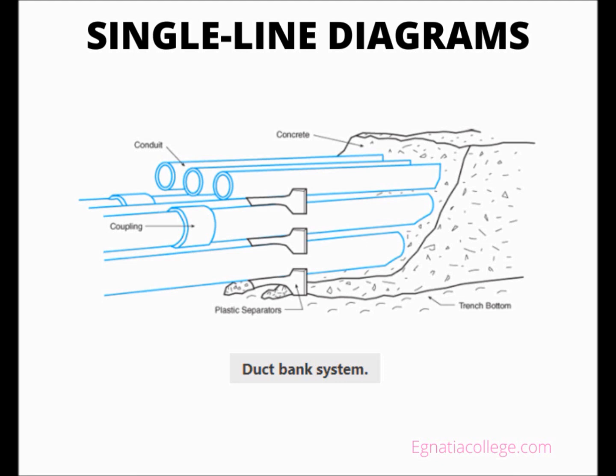And the existing electrical distribution plan on drawing E2 shows only a portion of the total electrical distribution section. This required notes 6, 7, and 8 to be added to drawing E2. Single line diagram E17, giving the contractor the lengths of the feeders for the elevator, panels L10 and L11, which are to be included in this school edition.